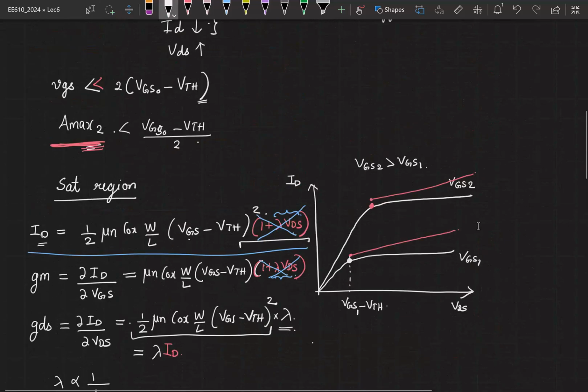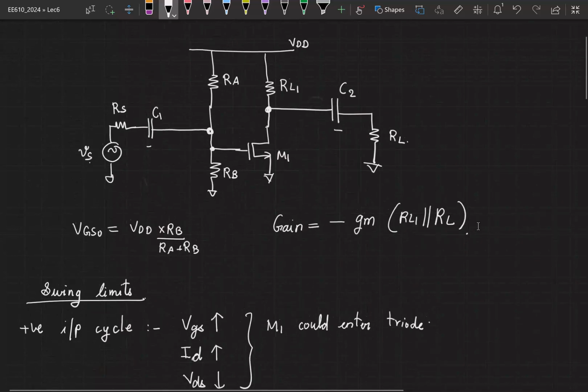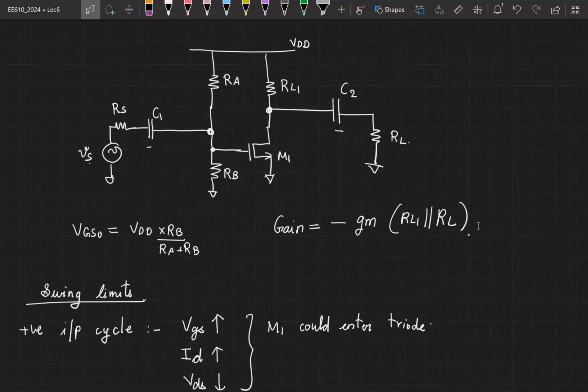So looks like we started out with a common source amplifier with this sort of configuration, right? And already we have hit a small bottleneck that the moment we take into consideration some of the transistor non-idealities such as the channel length modulation, the gain is now decreasing. So quickly I'll give you a value for lambda. Based on the numerical problem that we solved yesterday, could you tell me what is the new value for gain?